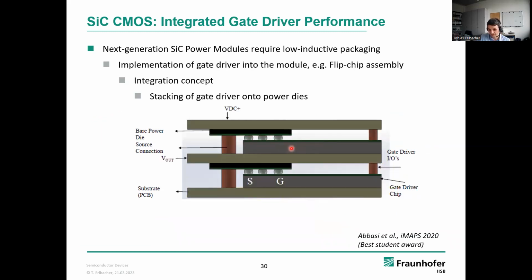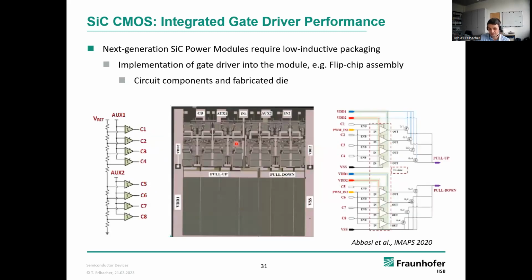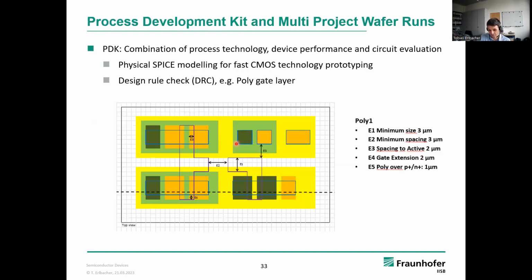So basically, if this device can go to 175 degrees, so probably will your gate driver. So it also should have the high temperature rating that is required here. And technically, silicon carbide power devices could even operate well above 175 degrees. But of course, due to the assembly technology that is available and the gate driving circuitry, this is usually not fully exploited at this point. And we typically stick to the same temperatures that silicon power devices are using.